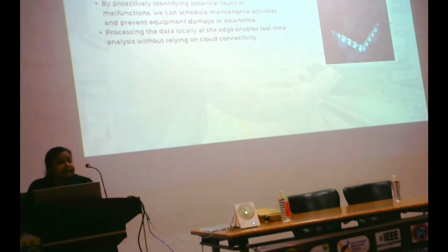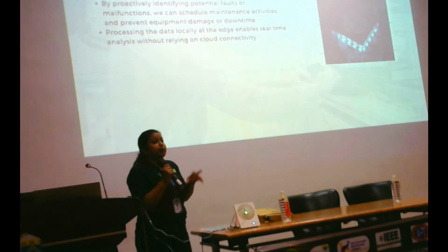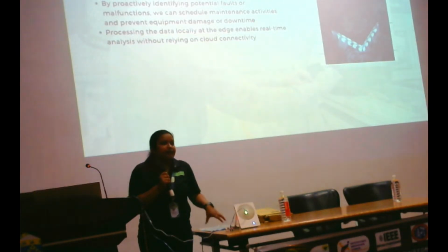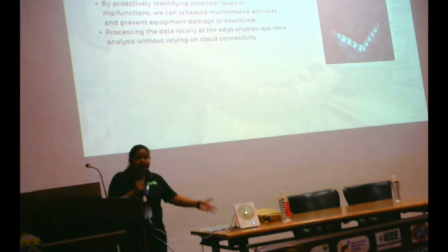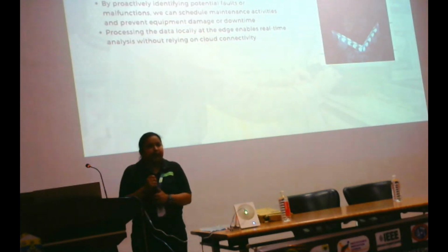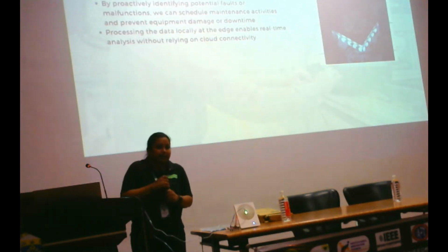The outcome will be that it will detect anomalies in real time, and you can perform predictive maintenance of any kind of machineries. Also, if you want to do cloud connectivity, you can work with Adafruit, ThingSpeak, AWS, or the Blynk app. All these IoT platforms you can work on, and you can transfer the data to the IoT platform. But this microcontroller is not capable of Wi-Fi initialization because the Wi-Fi module is not present. If you want to go for the IoT AI part, you can use a different ST board which is available, the AIoT board. In that you can perform AI models and also transfer your data to IoT cloud platforms.